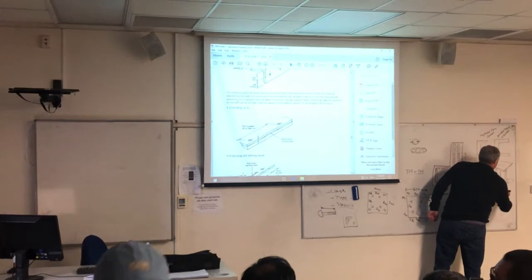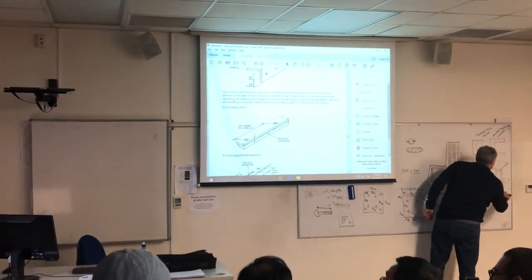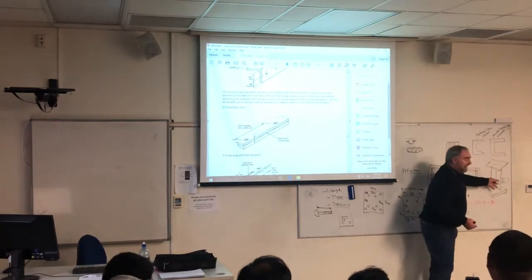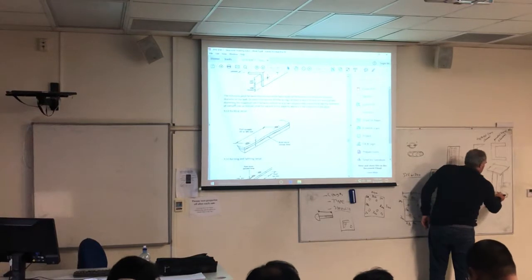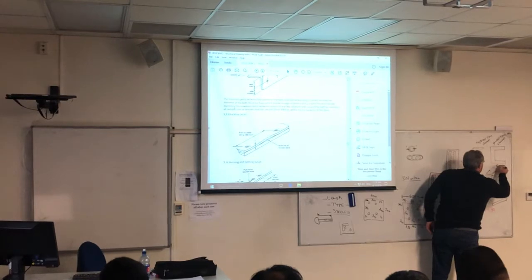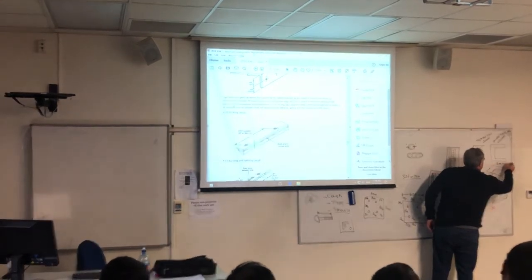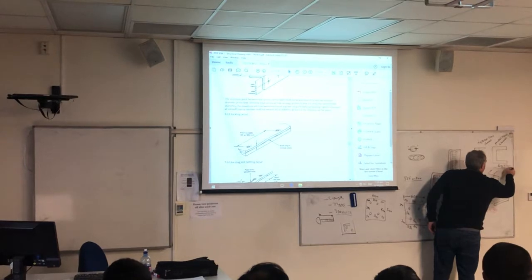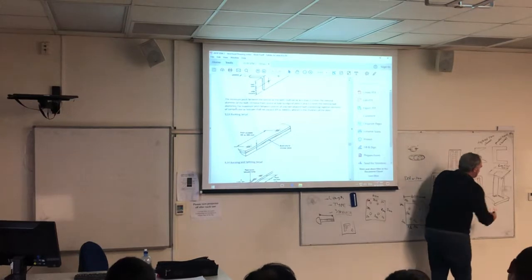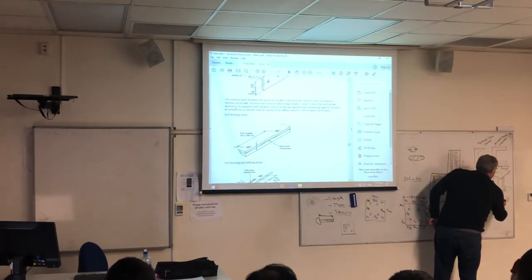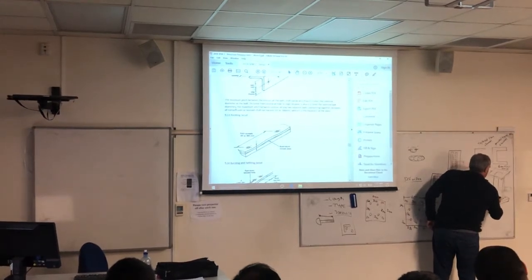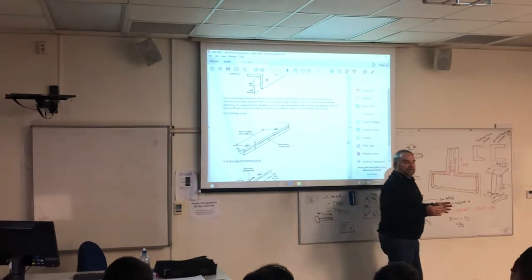The angle goes down like that, and there's another plate at the bottom. So the plate is welded on right the way around from the top and the bottom with a 6mm fillet weld. We'll talk about that in a minute as well. So looking down on that, you've also got your 2 holes, and you can put them anywhere you want around here as long as they don't breach the minimum or the maximum.